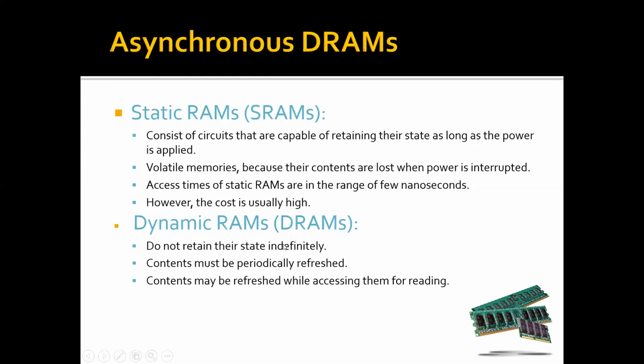Dynamic RAMs are less costly as compared to static RAMs. That's the only advantage of dynamic RAM. However, static RAM has many other advantages. It takes less power. Its access time is very low. However, the cost is very high in the case of static RAM. Static RAM uses transistors as the basic component. Dynamic RAM uses capacitors as the basic component.